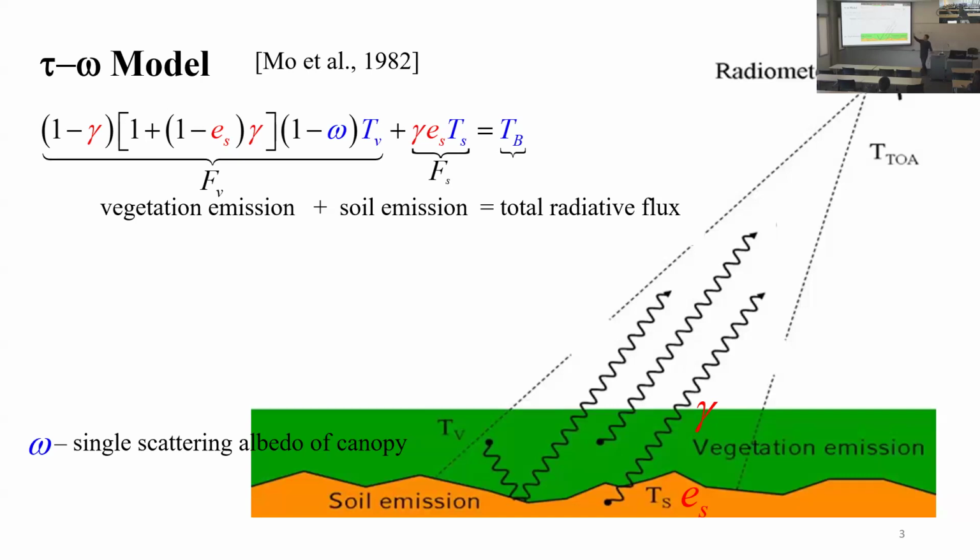So that's the simplified representation of this radiative transfer equation that relates to the surface so-called emissivity. That's what was needed. The emissivity characterizes the surface condition, to see how different it is from black body radiation. For black body radiation, we know from Planck's law, we can back calculate many other variables. But usually the materials we see are not black bodies. So how not black, that's characterized by so-called emissivity.